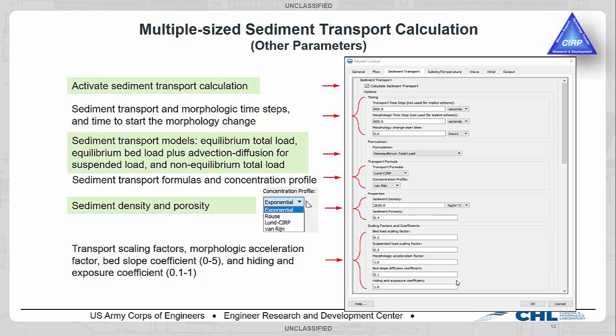And the interaction between the transport grain size and your bed composition can be affected by the hiding exposure effect. And for multiple grain sizes, of course, you have different grain sizes, and the big grain size particle might hide the small grain size. The effect is movement in the bed, right? So a big particle is usually exposed to the water, to the current, so it tends to move more than small grain size. So that's this whole hiding exposure effect function in the model.